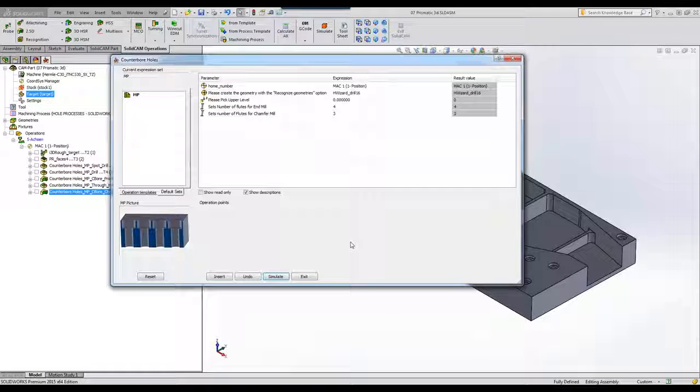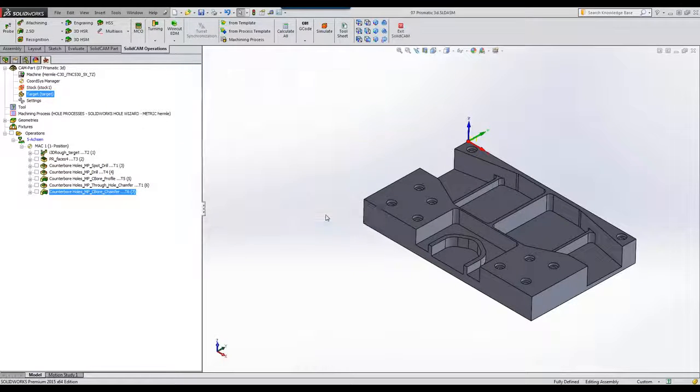Okay, now what we did over here is basically finish the entire part. I basically did three different things. I did my iMachining 3D, my finish with the pocket recognition, and I did all of these holes with the machining process, which created automatically 5 different operations.